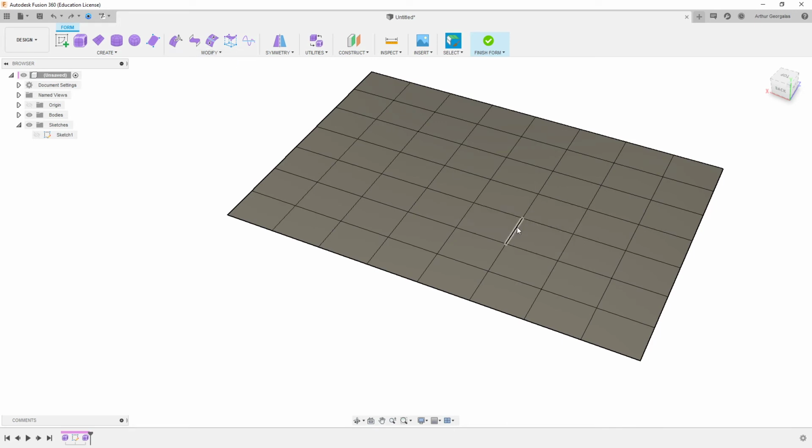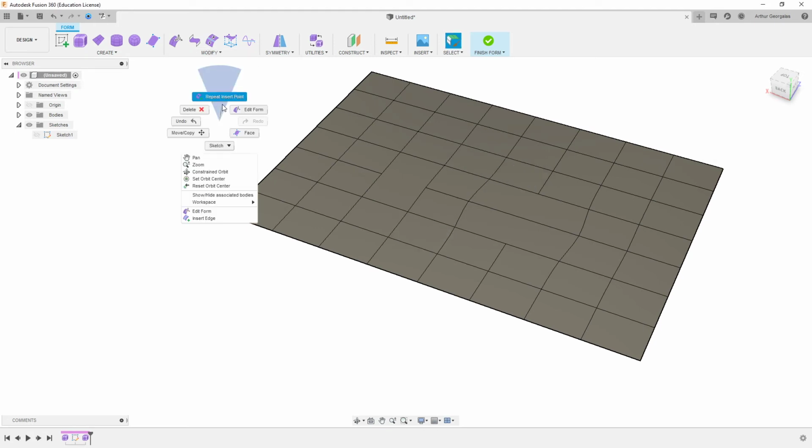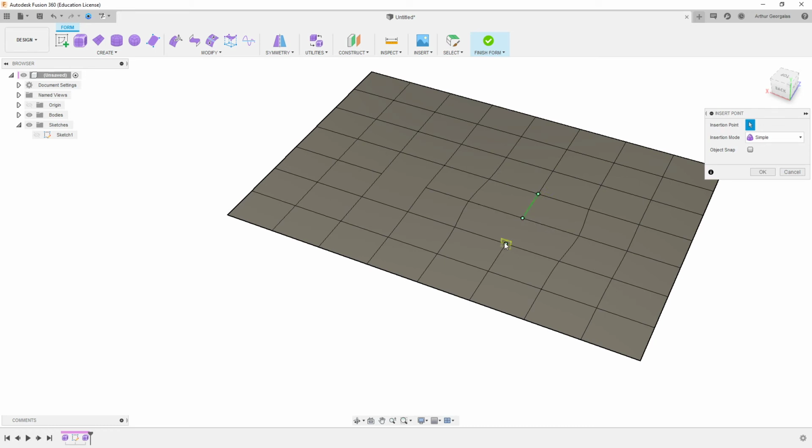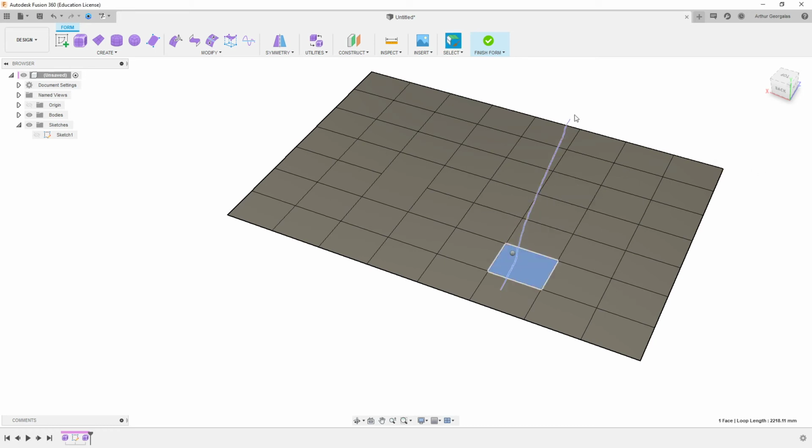And if there's an area on your model where for some reason you've modeled it up, and we can look at this, right? There are all these sections here where you've got faces that stretch out, and they have 1, 2, 3, 4, 5 sides. You can repair these by using insert point, by just clicking from one to another and going OK, and that's going to straighten that out a bit once we get that next one in. So repeat that. We can click through here, and here, and that straightens that out. Insert point for me is definitely more of a repair and control tool.